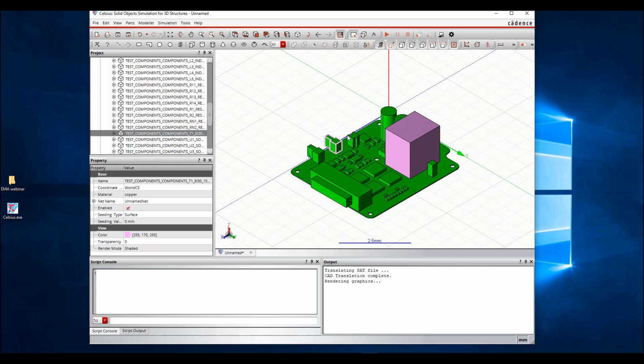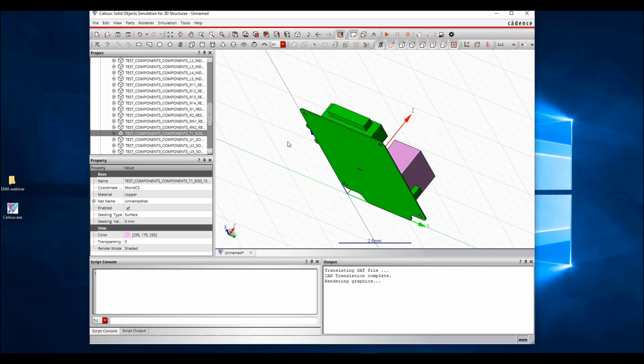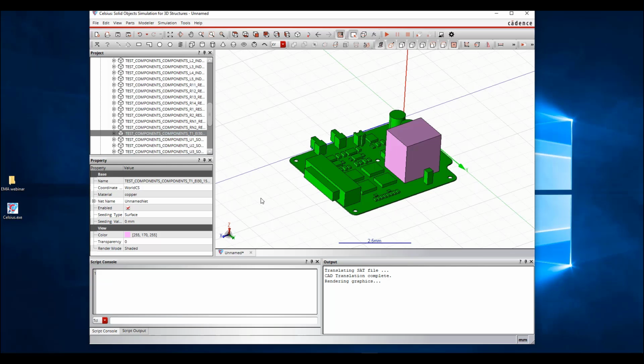Then after the material properties and heat in to the system are assigned, we can do the simulation from there. We could do CFD simulation. We can also do, say, if the bottom of this plate is attached to a big heat sink, and the heat sink is maintained at say 20 to 40 degrees C, then we can specify the temperature there. Or we can do CFD simulation. So next, I'd like to show you how we do CFD simulation on this example.